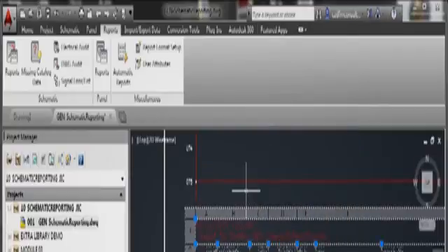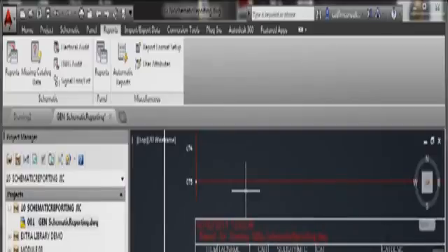So if I right click there, you'll notice I've got all the table styles, size columns equally, and so on and so forth. So I can actually edit the table style if I wish. At the moment, it's using ACE Table 1, which is a default AutoCAD Electrical table style. But I can change that. I can convert it to my company's specific table style, for example. I'll just hit Escape there to obviously deselect the table, but you get the idea. So that's how I can bring my report into my drawing.